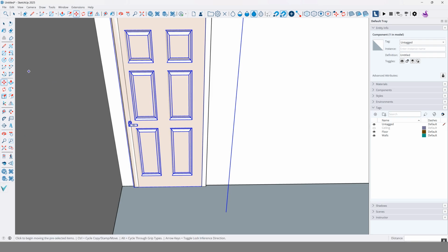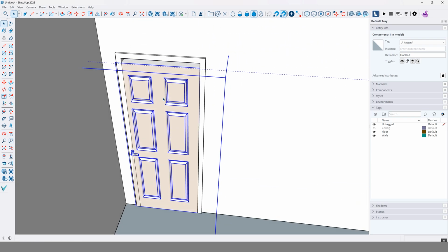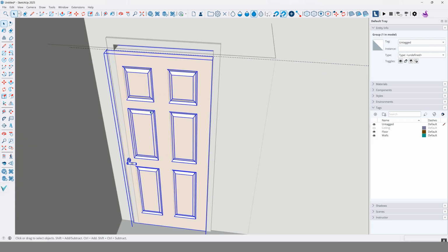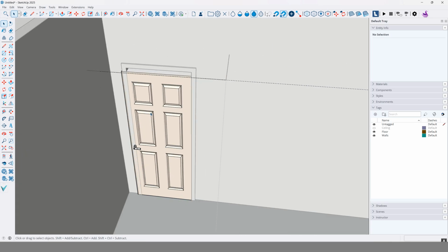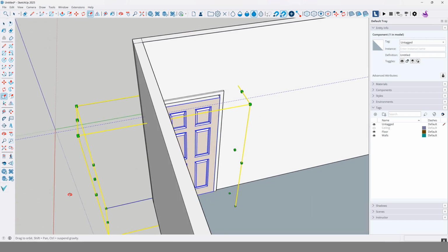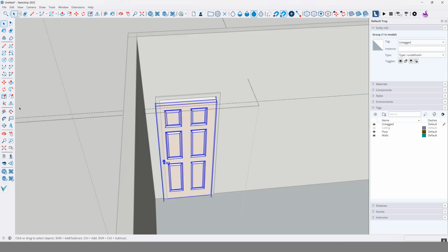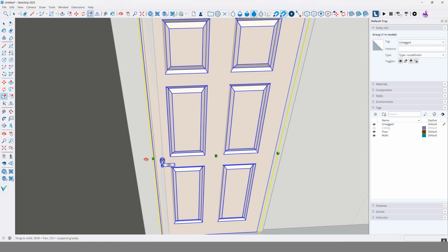Now what you'll see at the moment is the door doesn't currently quite fit, because whoever drew this originally has drawn the door dimensions differently to the door hole that we have done. So you've got a few options here. You can, if you're not too worried about the scaling of it for now, just use the scale button here, select it, and select the edge of it and drag it across. So let's open up the door, let's grab the scale button.